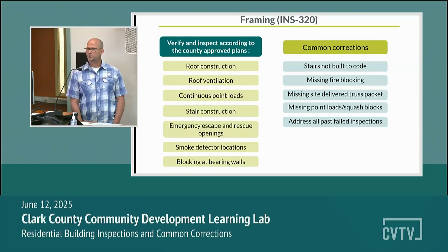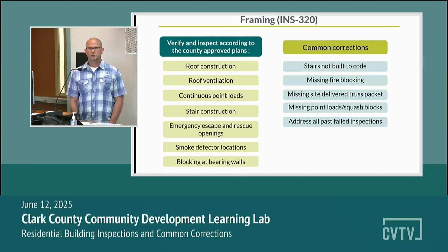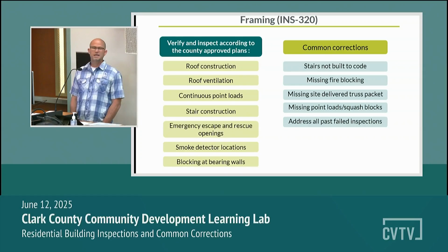But you'll say, hey, I turned in a truss package at the very beginning to Project Docs. Well, as the project goes on, those trusses might have changed a little bit. It might have gone from a double girder or double truss to a triple, or something else might have changed. So we need those on-site trusses to look at. And so that's a simple correction, or that's a correction we write that could simply have not been written had those been on site.